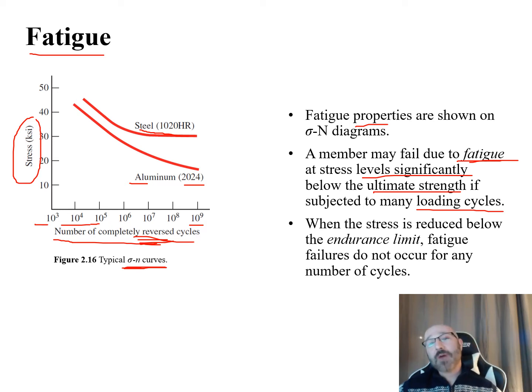Another thing to think about when you're talking about cyclic loading is how quickly you get up to that, in my case here, 200 pounds. It's not something I want to do at maybe a quarter inch a minute. Maybe it's every 2 seconds, every second I go up, bang, bang, bang. So all of a sudden you might not be able to use one of those lead screw machines. You might need one of the hydraulic or pneumatic testing machines, where you can quickly do 3 years' worth of testing over the course of a weekend or something like that.